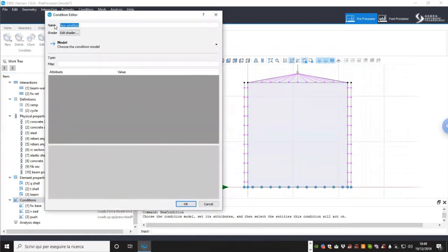Or even, okay, now in this example, the wall was perfectly connected to the beams. Now imagine you're modeling an infill, you can use the same concept, but to define a cohesive interface between the beams and the wall, for example, if the infill is not perfectly connected. Now, in this case, it is perfectly connected, so we just create an equal DOF between beam and wall.